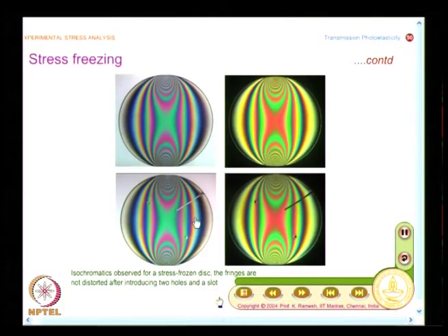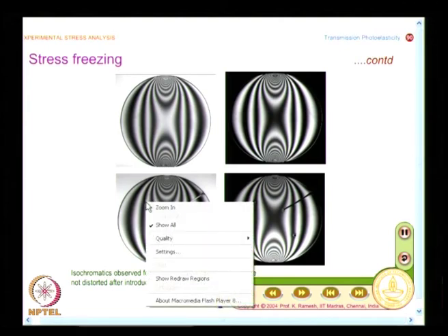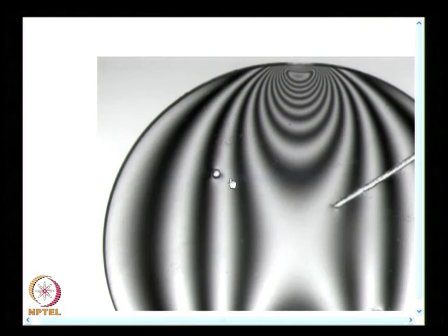That is very important. The second aspect is, by careful machining, it is possible to cut slices which retain the stress distribution. This is shown in color, and you also have the patterns recorded in black and white, because in black and white, even if I take this hole, you would not see that subtle difference. I said that hole machining could have been improved slightly better, and when you see a black and white fringe pattern, you will not notice that the hole has some small minor issues.